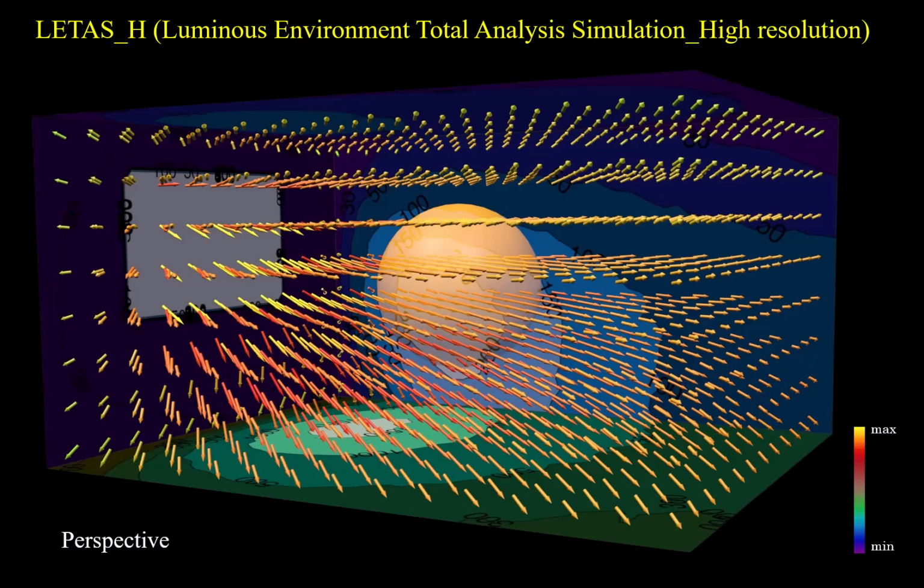Whatever the method of simulation, it is important to design the luminous environment using absolute values rather than relying solely on the senses in order to carry out objective lighting design. Especially in future lighting design, where the SDGs will be emphasized, it will be necessary to consider detailed, human-centered luminous environment and optimize energy consumption. For this purpose, we believe that a comprehensive lighting design method using absolute values of various evaluation factors will be an effective approach.